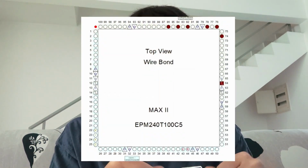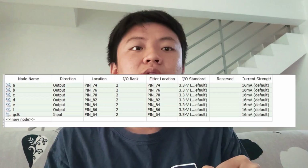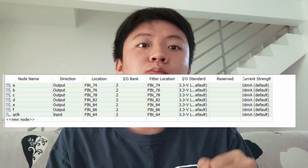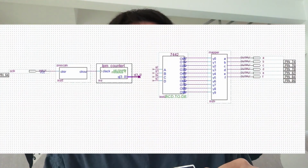Now we step into our last part, which is 2.7. We start programming our CPLD. First, we assign our device to EPM240T100C5, according to the construction manual. Now we want to set the pins. First, we set pin 64 as our input G clock. Then we set pins 74, 76, 78, 82, 84, and 86 as our outputs, which are A, B, C, D, E, F respectively.